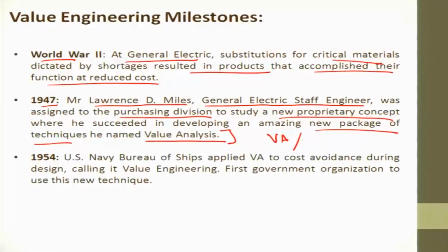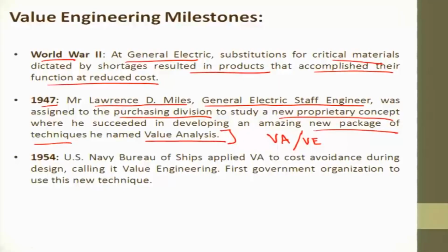These days value analysis and value engineering are used interchangeably, though there is still a debate going on that value analysis is different from value engineering. Some contributors say that value analysis is only up to the analysis part. If we identify the functions, establish the monetary value, and find the unnecessary functions, that is value analysis. And if we take it forward, eliminate those unnecessary functions, and provide a new plan for the product in which those unnecessary functions are not present, this is value engineering. So this line between implementation and analysis makes the difference between value analysis and value engineering. Some of the authors would say value analysis is now value engineering only.